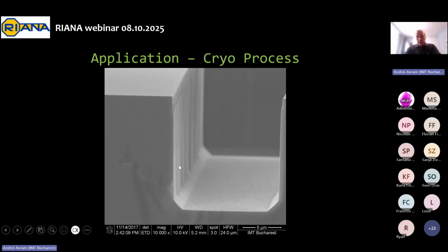So as you can see, the cryogenic etching is very, very smooth. These vertical lines here actually are not from the etching itself, it is again from the photoresist, because in this case we've been using photoresist as a masking layer. And this time, because of the very low temperatures, the photoresist actually contracts, and we again get these structures. But you can also use hard masks in order to improve the roughness of the walls if your application really requires very smooth sidewalls.